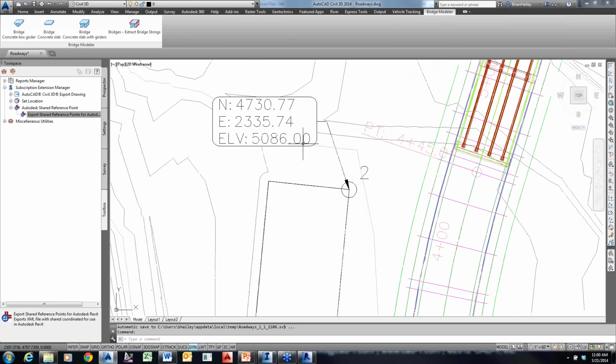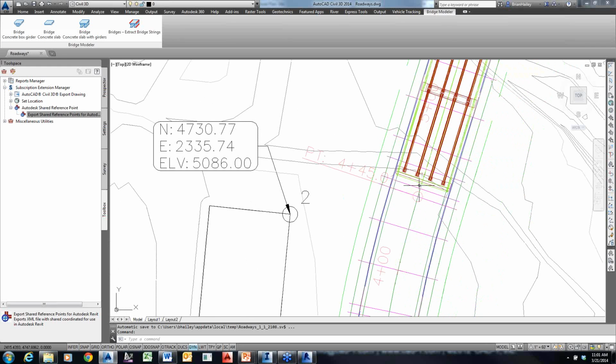But that's really coming in, having this coordinate system going down. But you're going to have the civil engineer establish where that base point is going to be and linking this particular project in. We can see in here that right about here is the start of that bridge. That's where, or right here, is the origin point of that bridge. And then I'm going to pick the origin point for the building. The reason we did the start point of the origin for the bridge here in Civil 3D is because, remember, the bridge tool brings the model in either at the center, or we can dictate where along the alignment that origin point's going to be.